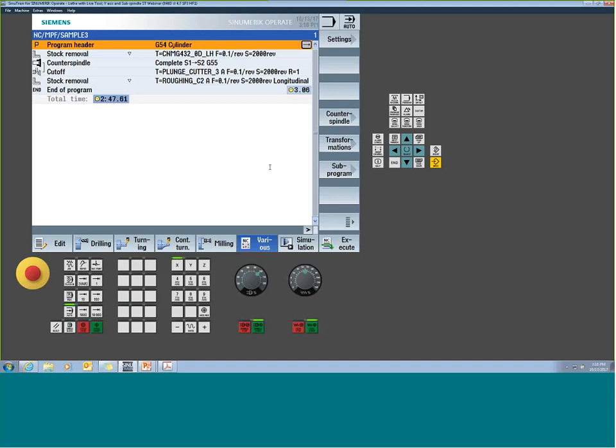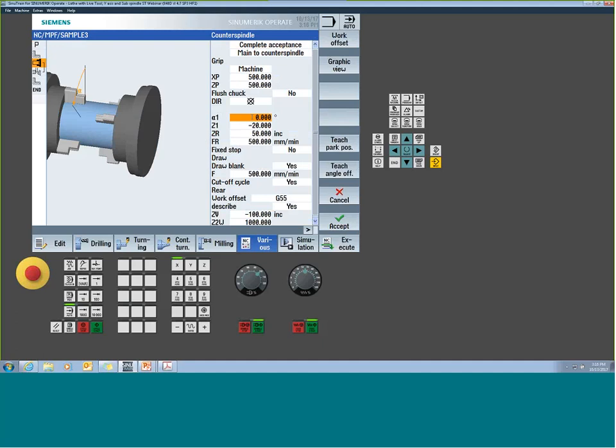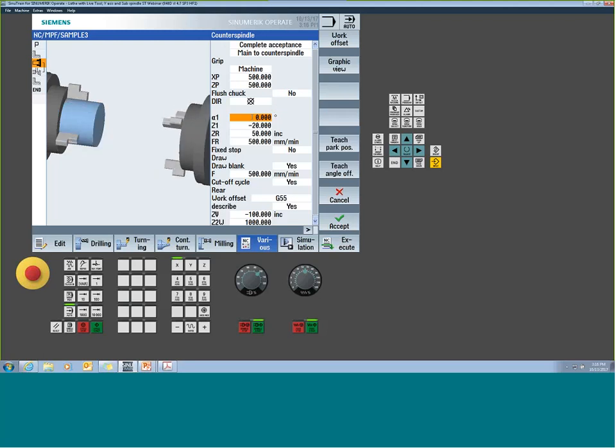How can I figure out where my chuck orientation is? This is a good question. We talked about that one little feature where I can do an orientation angle right here. Well, step one is, how do I know if my jaws are going to collide? When these chucks get bolted on, some of them have drive keys, some of them don't. But even if it has a drive key, we don't necessarily know that spindle orientation 0 on the main and 0 on the sub are going to have those two jaws lined up.